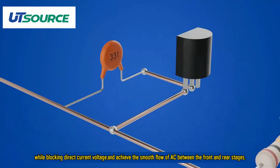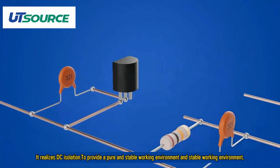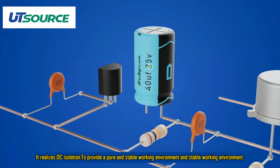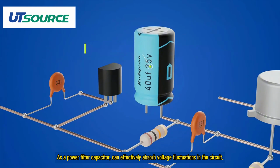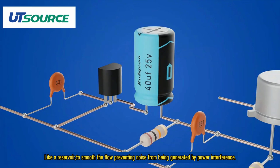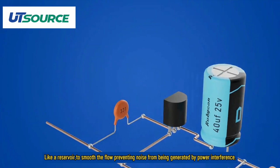It realizes DC isolation. To provide a pure and stable working environment, we add a 40 microfarad 25-volt electrolytic capacitor. As a power filter capacitor, it can effectively absorb voltage fluctuations in the circuit, like a reservoir, to smooth the flow, preventing noise from being generated by power interference.